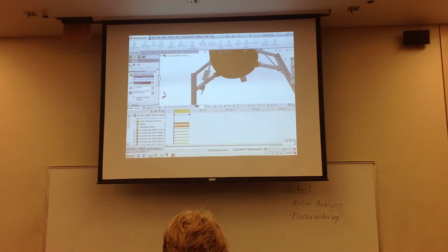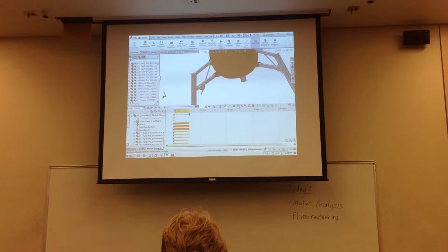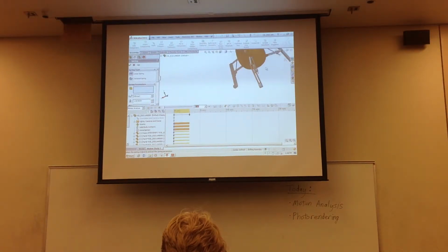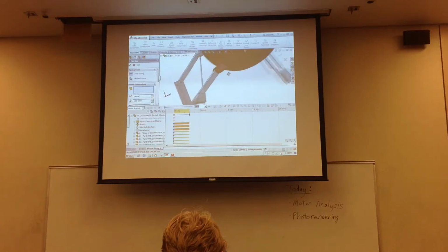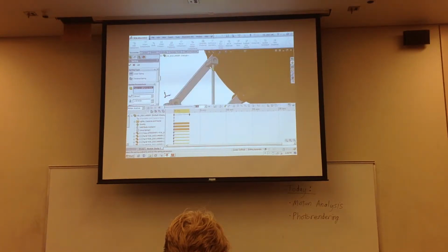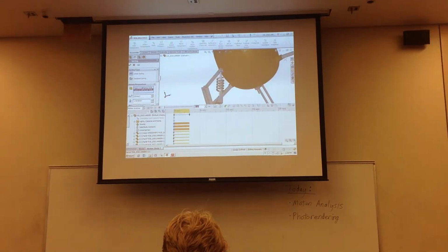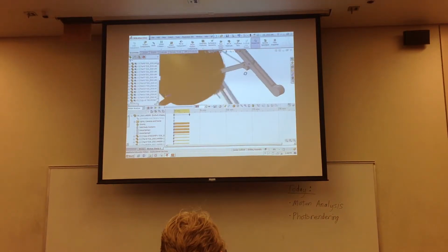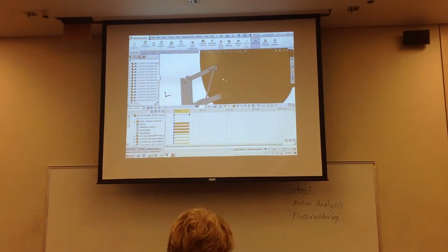Okay, so let's accept that for the first spring, and we need to simply repeat that same process for the other legs. It saves some of our settings, so we can just click the new surfaces for that one to act between. It saves the display settings and the value of K. We'll say OK, and then do it for this last leg.